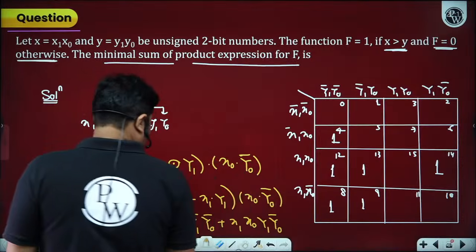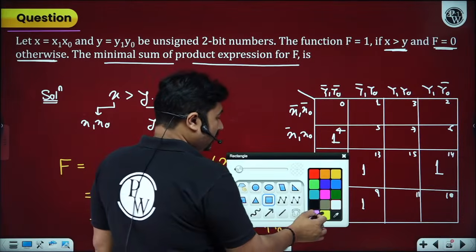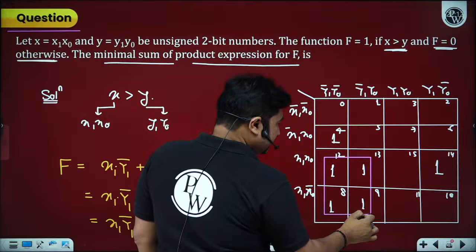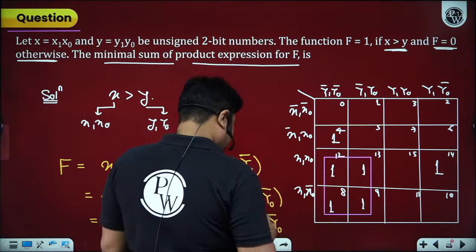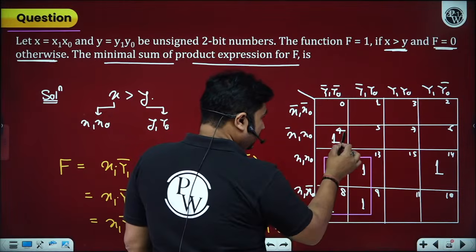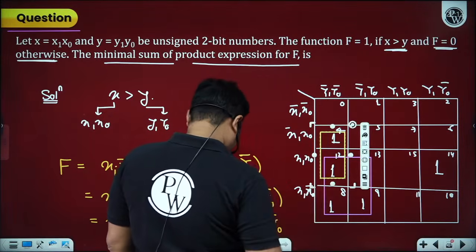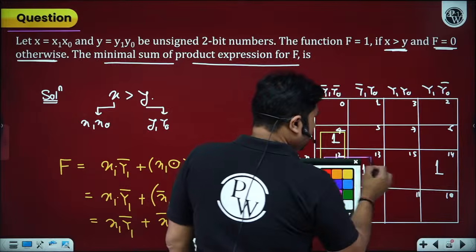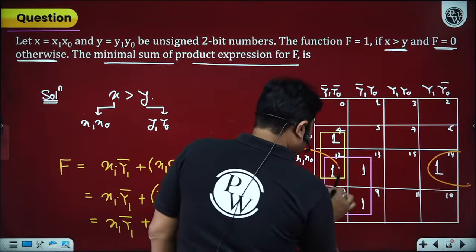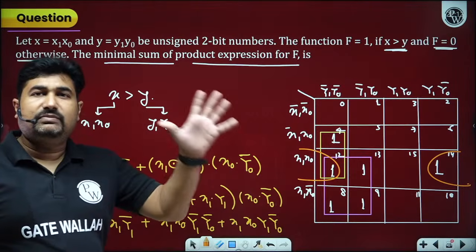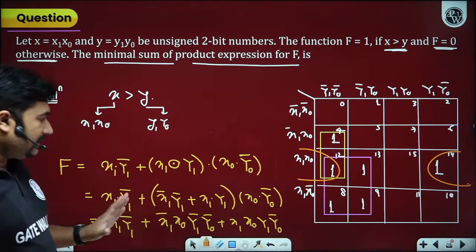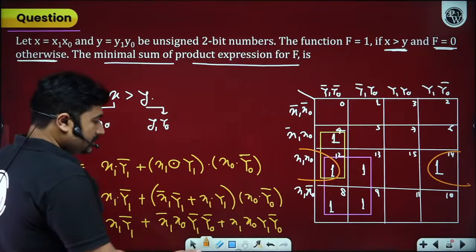Please observe. Beta ji, we have this cube in the minimized expression and we have two pairs. One pair is possible, this one, and the other pair is this one. How many of you can observe this? And now you also know how to identify the minimized expression for any given Boolean expression. Is it okay? Yes, sir. So now please observe.